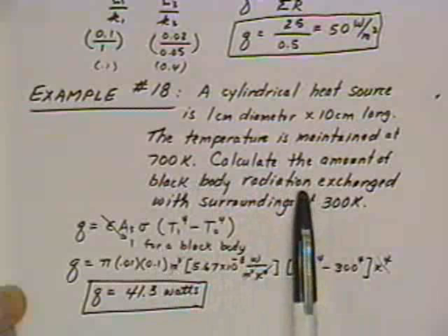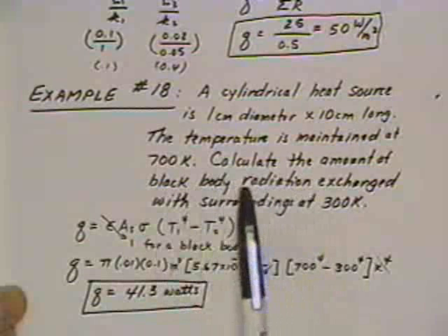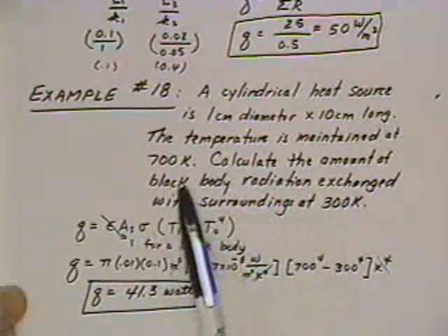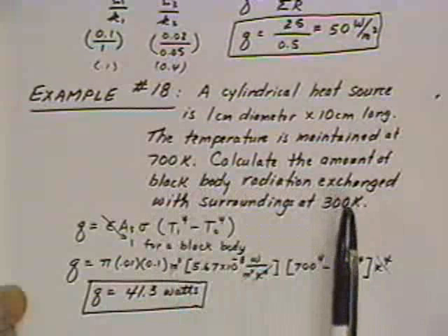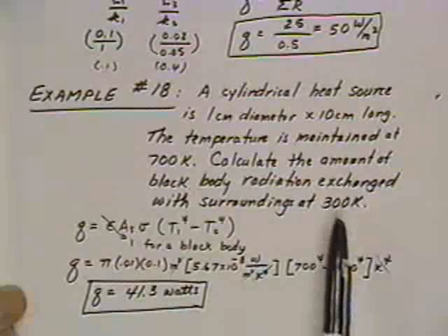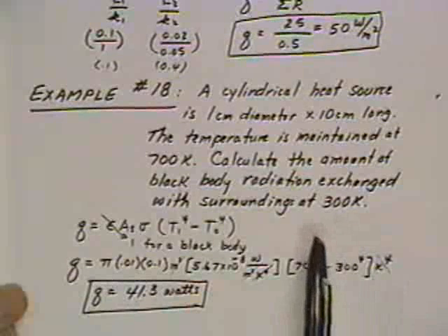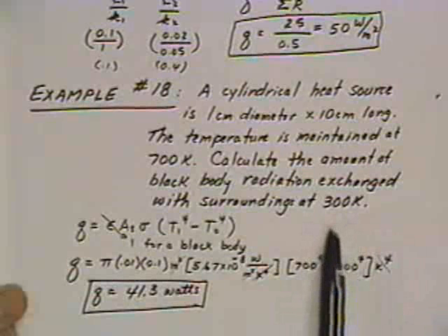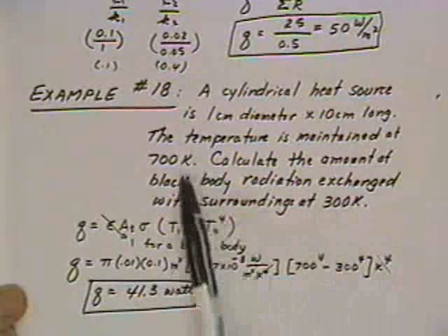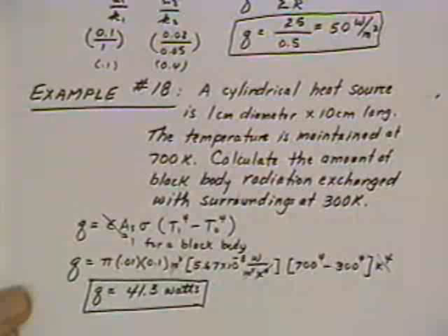So that means that's the most efficient radiation that we have, that there are no losses in the amount of energy that escapes the body. And so we've got an equation. The principal thing in dealing with radiation heat transfer is that you're working with the 4th power of the absolute temperature. And so again, another admonition, make sure that you're converting your temperatures to absolute temperatures. In this particular case, I made it easy because I gave them in degrees Kelvin to start with.